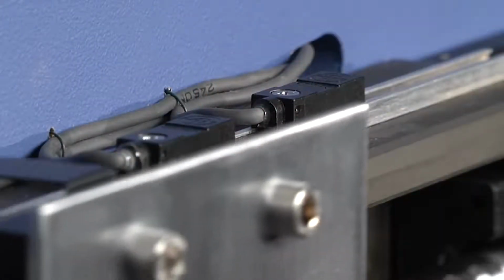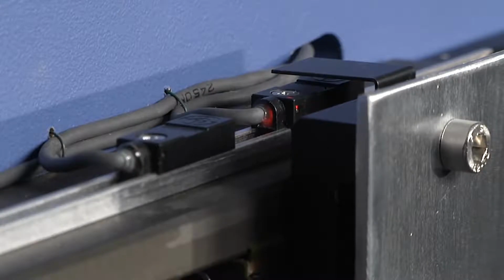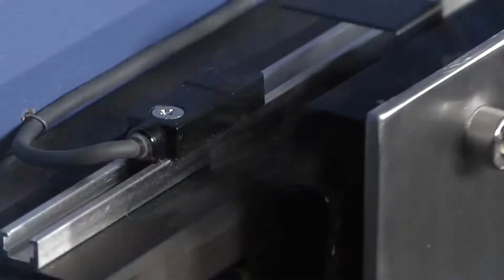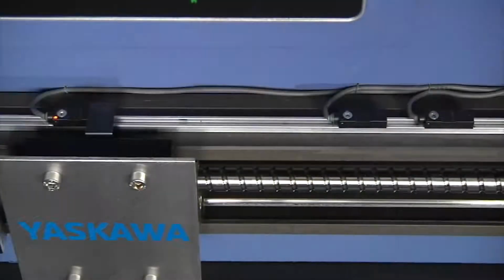A properly programmed controller should prevent the machine from ever getting close enough to reach these sensors, but experience dictates the wisdom of planning for the unexpected. Overtravel inputs can prevent costly damage. Without it, moving parts of the machine could be allowed to crash into one another.